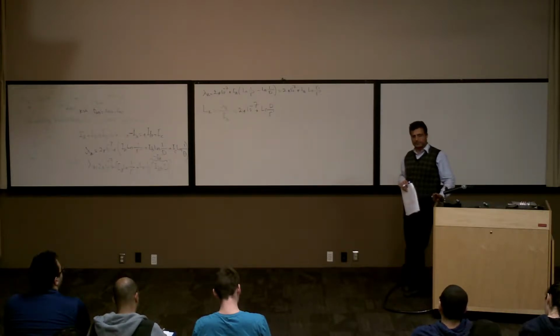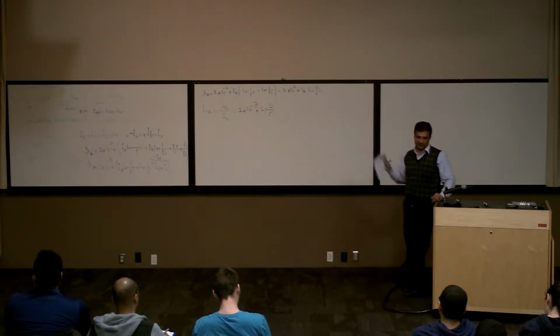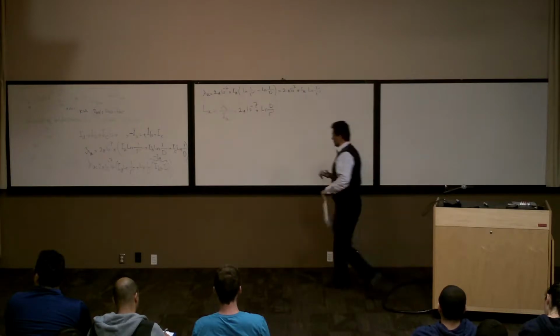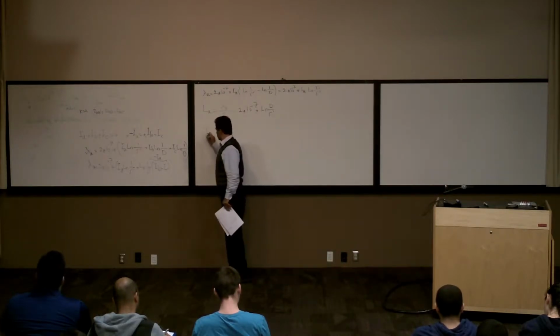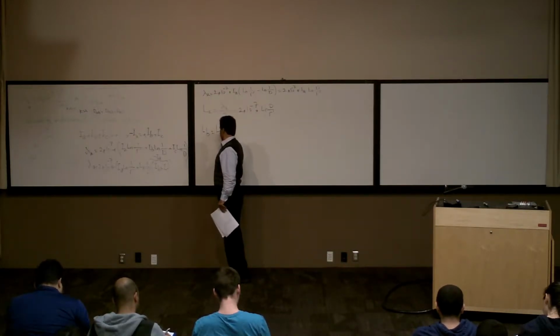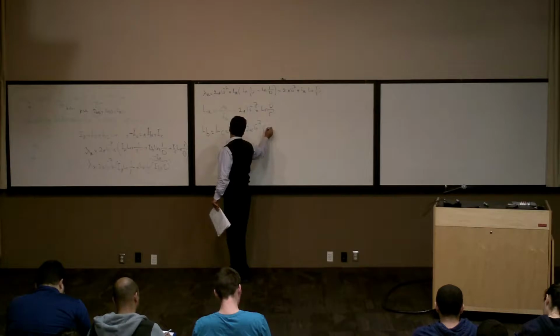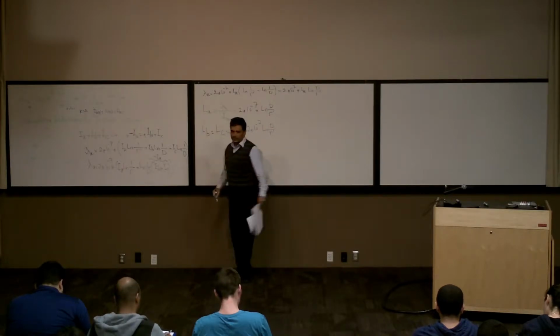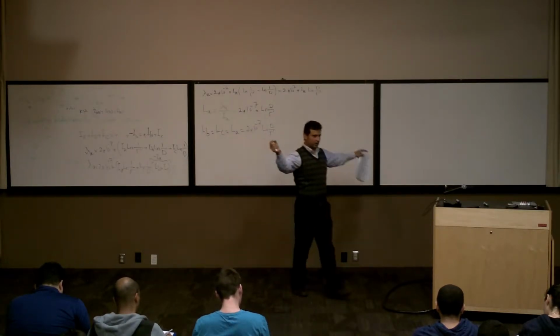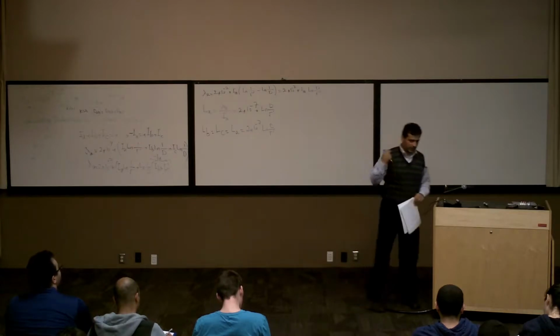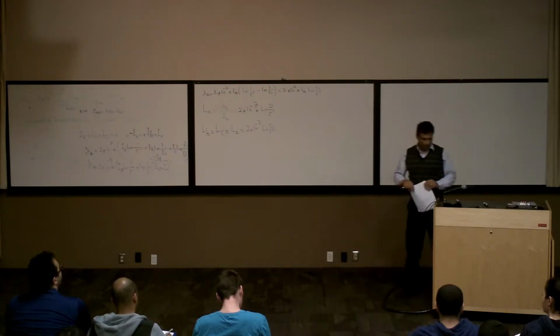How much is the phase B? Phase B is the same, right? Because it's going to be the same distance, so it's going to be exactly the same. So LB is equal to LC is equal to LA. So basically 2 times 10 to the power of minus 7 ln of d over R prime. So now we know how much inductance we have for each phase, and we calculate it out.